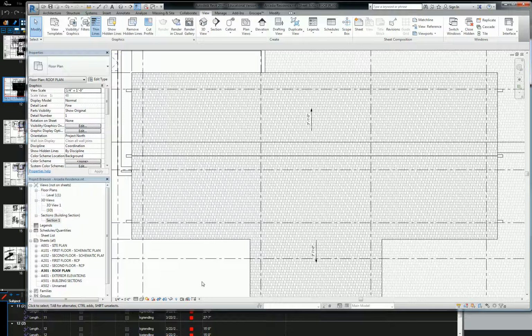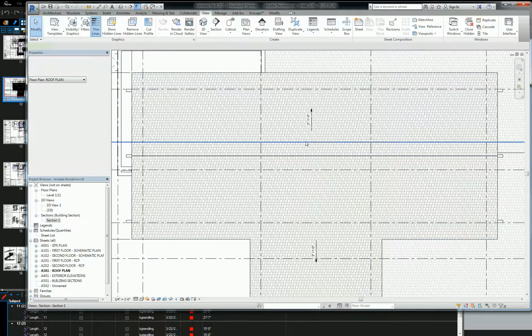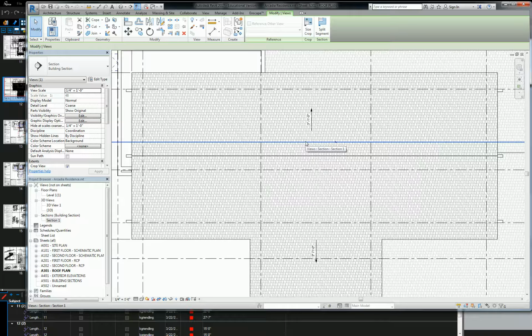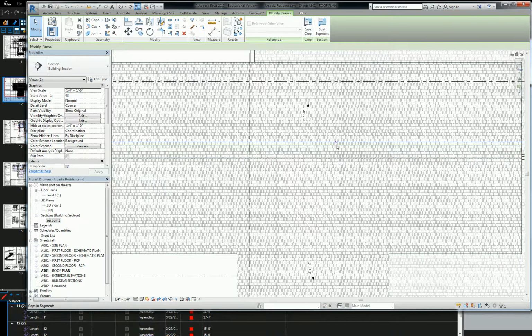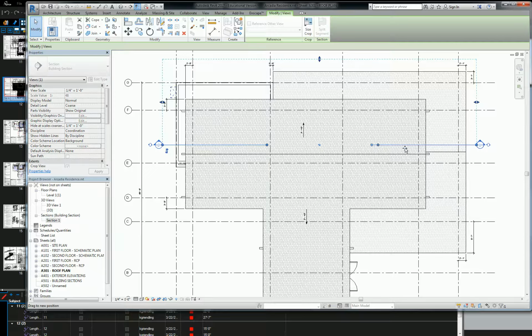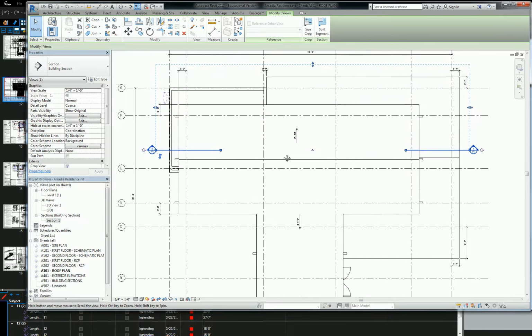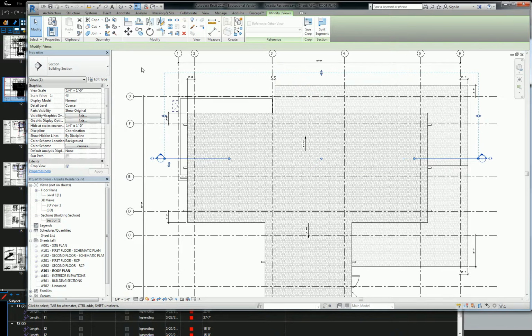So what I think stylistically makes the most sense for a building section is this little cut button here. It's super tiny. You guys can barely see it on this screen because the resolution's so low, but it's a little squiggly. You're familiar with break line symbols. You can click that little squiggly and it breaks that line into pieces, and you can pull these back, and that is a properly calibrated building section. Simple. Okay?